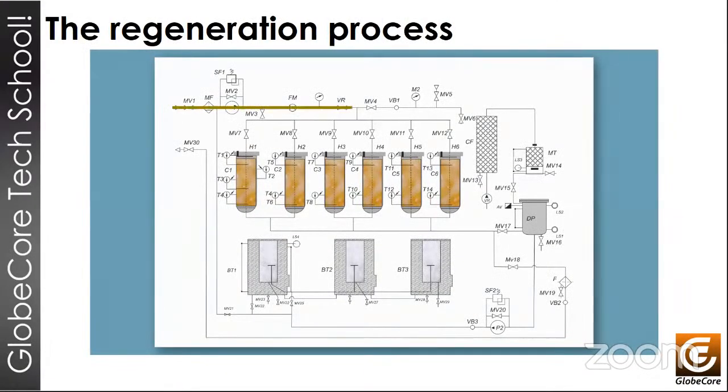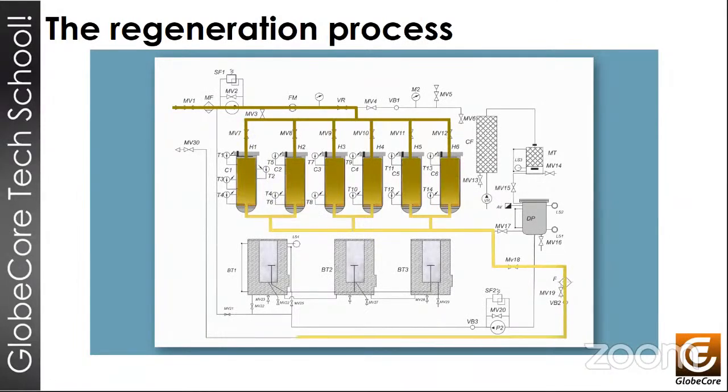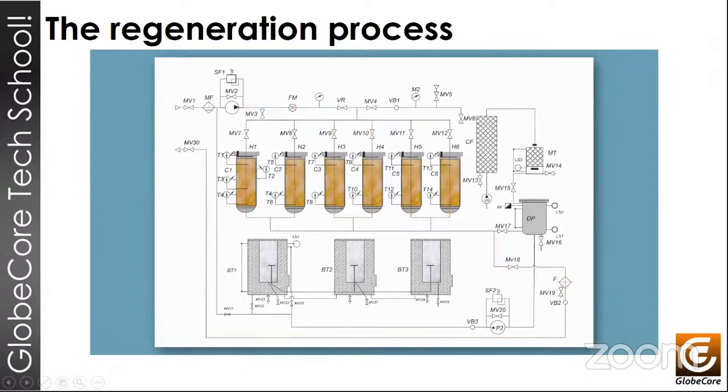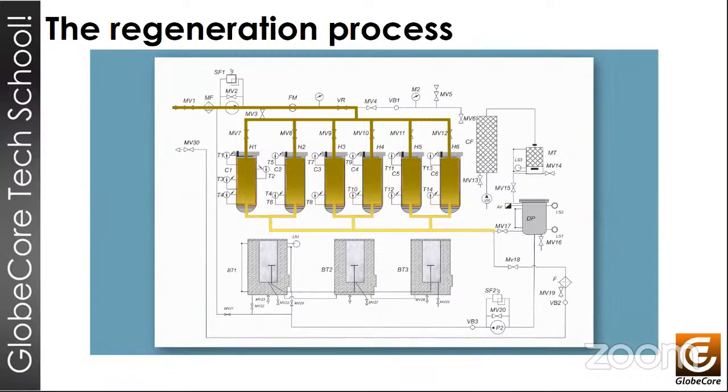Right. So in this animation, we can see how oil is pumped and distributed to each of the columns with Fuller's Earth. And once the oil passes through the Fuller's Earth, it's returned to the transformer, or maybe we work from an external tank, so we can return it to the tank. Depends also on our setup. The amount of the oil that we can process in one time depends on the quality of the oil before we need to reactivate the sorbent.